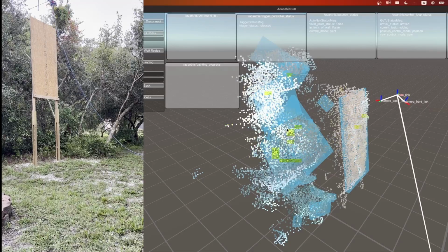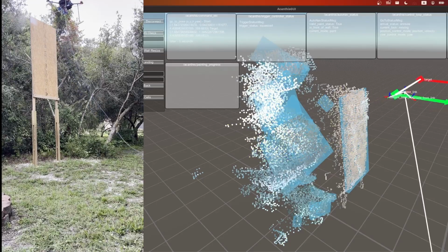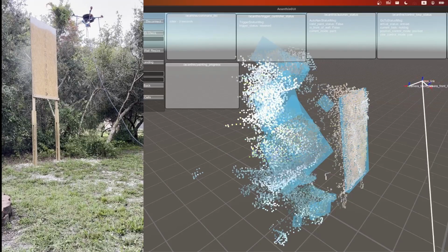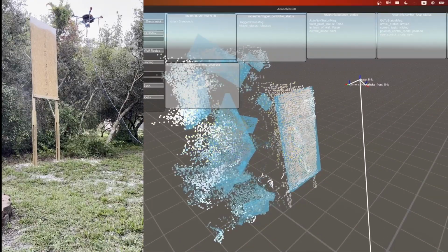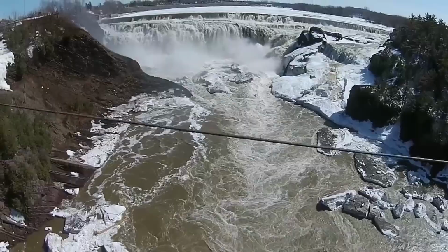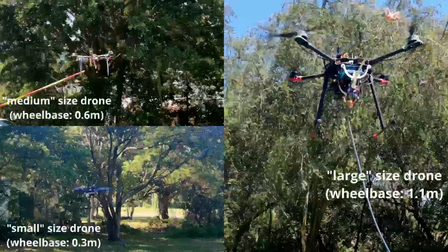In addition to this lower level model for controls, we have also made a high level machine learning model to handle navigation, which can be seen in the window on the right. We built a pipeline that can take in data from all types of sensors and feed it into this model. This top-level model can then handle commands from code or an RC controller to perform autonomous navigation and obstacle avoidance. This means you can tell it to go from point A to point B without worrying that it'll run into a power line, tree, or even a moving object.